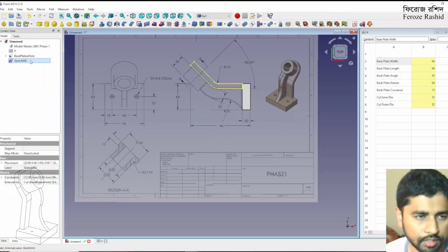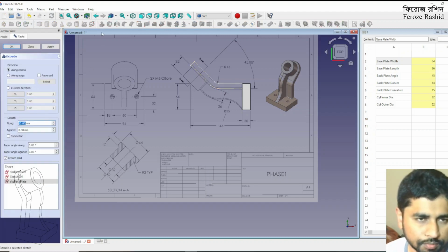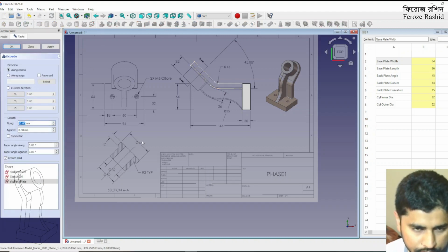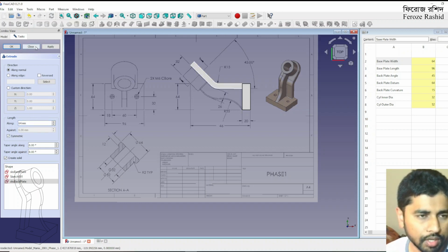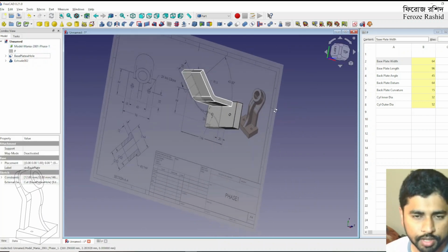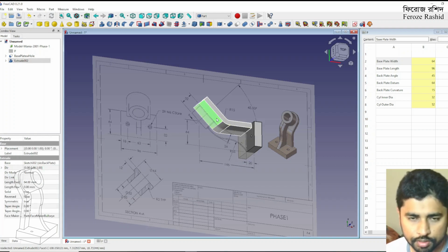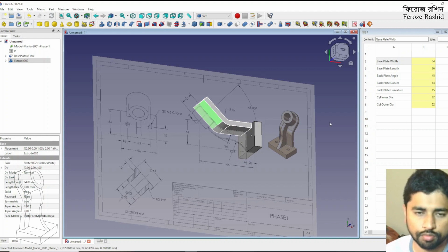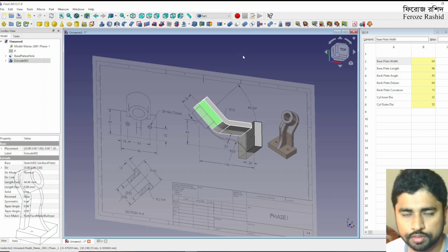Let's close it, and then I'm going to say sketch back plate. And I want to extrude that by, you got it, 64, and it will be symmetric. Apply, close. So there it is. That's our back plate. The next thing to do is either this cylinder or this spline, this reinforcing spline. So let's take care of this cylinder first, because I want to make this workflow smooth, and having the cylinder built would help us explain things.